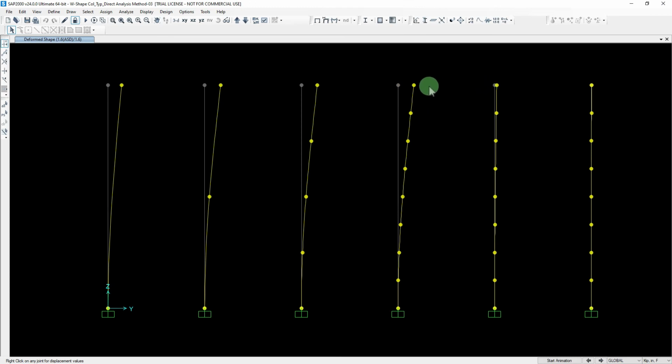You can see what was previously, it was like 7 under the 1.6 load, but these are the real ones. These are the real deflections. So we have 5 inches, and this one right here is less than an inch. It's almost 3/4 of an inch. Still probably not something that I'll be comfortable with at 3/4 of an inch, but it's tolerable.